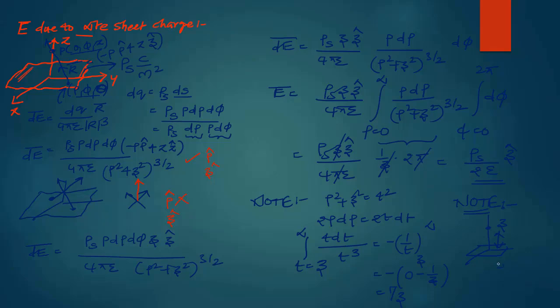But if you see the electric field expression, rho s is fixed, uniform, we have taken charge density, 2 is constant, epsilon is also constant, and z cap. So everything is constant only. Constant by constant means you will get a constant electric field. With respect to distance, the electric field is not decreasing here. But in case of the point charge or the line charge, you can understand that as you increase the distance, the electric field intensity reduces. But in this case, it maintains a fixed value.